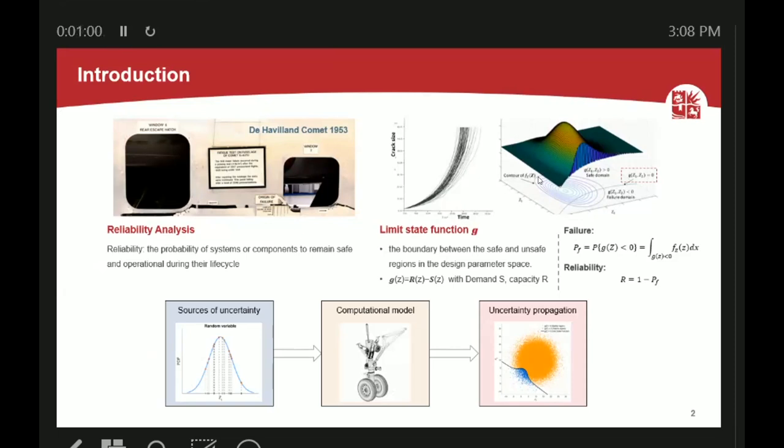So now if we're looking at the fatigue testing here, even if we're starting with the same initial crack size, we may end up having a different fatigue failure line. This is because we have variations in material properties, geometry, and even loading conditions. So nowadays, reliability analysis or probabilistic analysis is often demanded so that we take into account the scattering nature